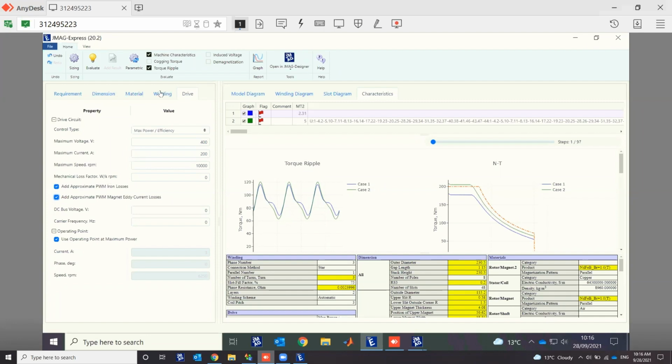And afterward, for the efficiency map, you have access again, like in Designer, to algebraic approximation of PWM losses and magnet losses by changing the DC voltage and the PWM frequency. So those are algebraic or analytical approximations of the losses that you can have. But for the ROM, I will come back to him directly if he wants more precision.